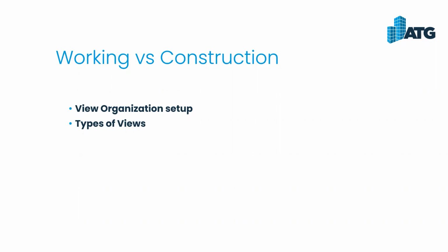Those can be developed in your view templates. So if you've got a good set of view templates now, you may want to utilize the view classification aspect of it. That way, the project browser will automatically do that when you set up your organization for your project browser. Now also, with that view organization, you want to set up the different types of views.